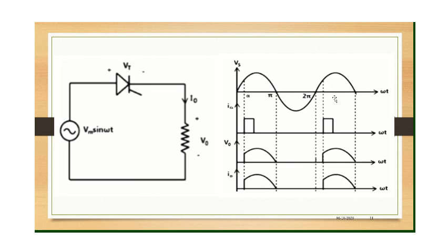Again, when it reverses, when it goes positive, at this duration, you can see till this time the SCR is not turned on. Why? Because you have not applied the gate signal. So once you apply the gate signal, the SCR is turned on, and the same voltage that is supplied is visible at the load.